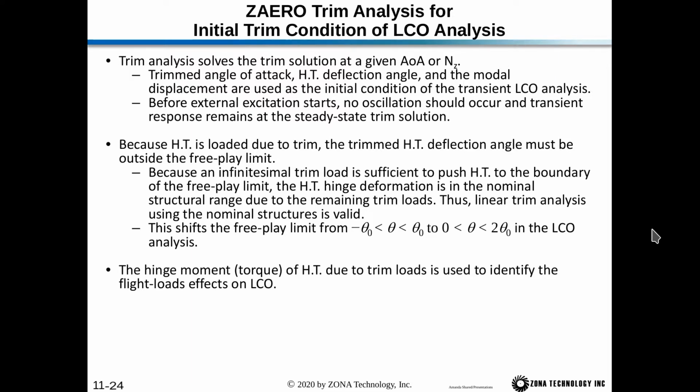And because an infinitesimal trim load is sufficient to push the horizontal tail to the boundary of the Freeplay limit, the horizontal tail hinge deformation is in the nominal structural range due to the remaining trim loads. Thus, a linear trim analysis using the nominal structure is valid. And this is going to shift the Freeplay limit to plus or minus theta naught to in between 0 and 2 times theta naught in the LCO analysis.